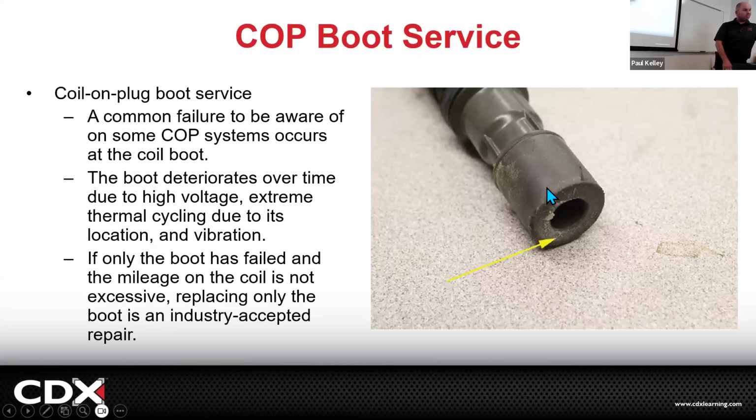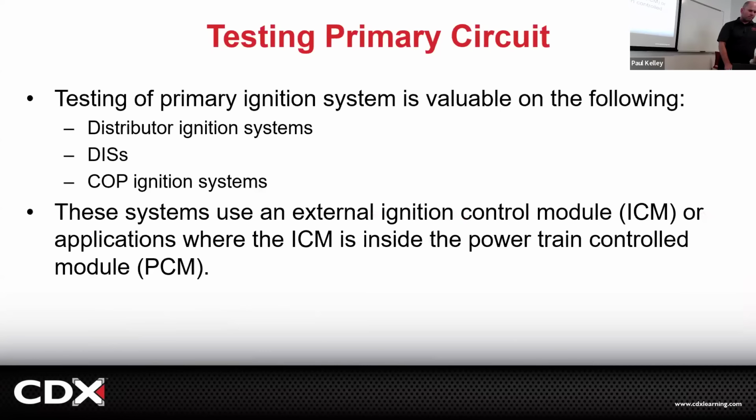To be honest with you, we typically don't do the boots. If the coil fails, we do a coil, which comes with a new boot. But it wouldn't be a bad idea to do periodic maintenance of the boots. I just don't know how many miles, because the manufacturer doesn't usually call that out, right? You might just go in preventatively and say, let's do new boots, but you're on your own on that call. The manufacturer most likely won't tell you to. Cool, but it's a similar failure.